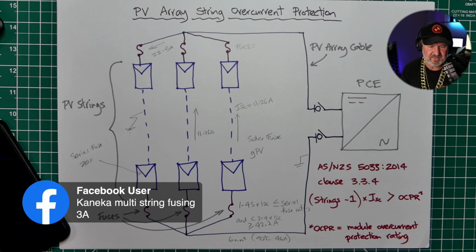And a Facebook user says we have masses still going. Yeah, nothing wrong with them. In fact, I've actually repurposed a lot of them for shade devices on the side of my house and on the side of my shed, and they're connected to inverters. It's just that they take up a lot of space for a relatively small system. But yeah, nothing wrong with them. Amorphous silicon was very popular in the day. It's sort of faded from popularity because of the poor conversion efficiency of only about 7 to 10%.